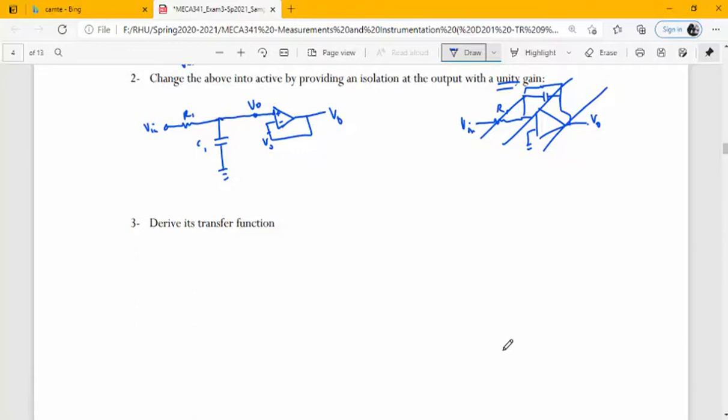This node is called V output because we know that in an ideal op amp the two terminals have equal voltages. They have very high impedance inside the op-amp, therefore we have equal voltage, and the current passing through it is equal to 0. So we will be using the energy from the power supply of the op-amp.